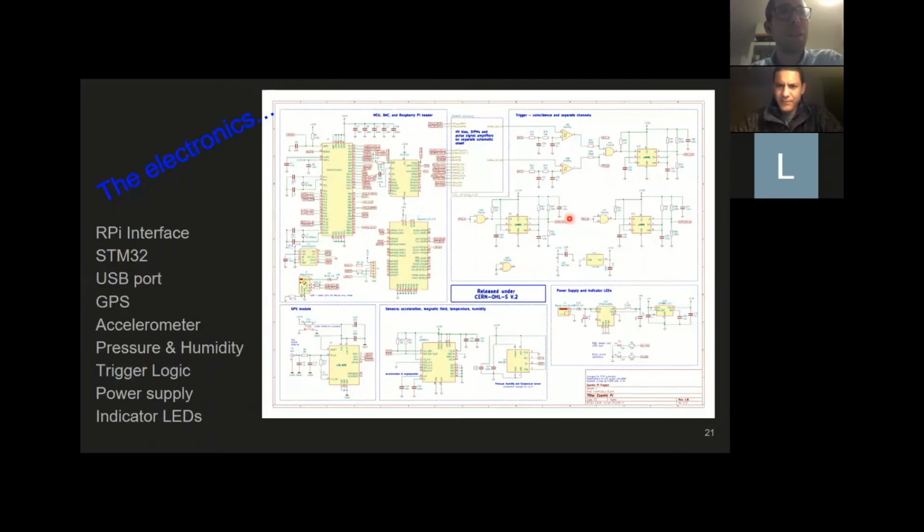We also duplicate this circuit for channel 1 and channel 2 independently. So this means that when we're building the detector, we can also do some calibration. We can look at signals from one channel independently of the other channel, which helps us to tune for the rate and also to make sure that we don't have too much noise.